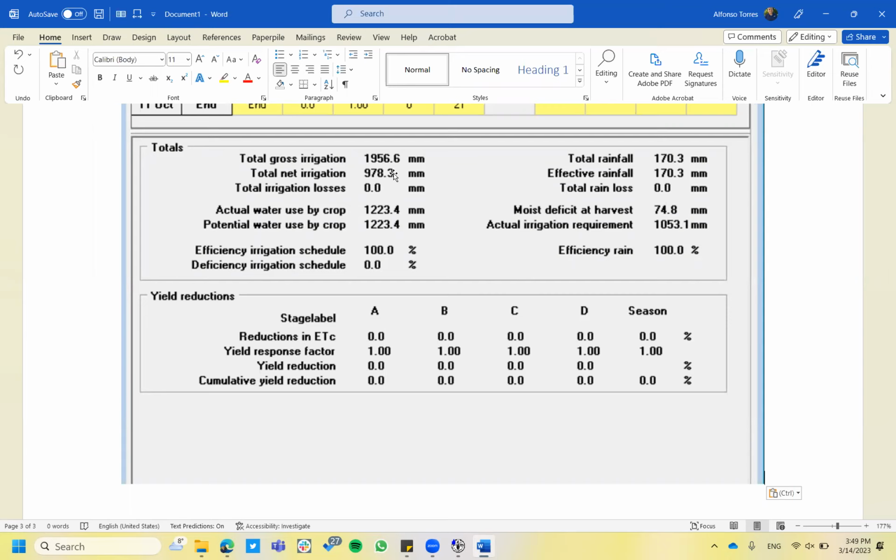So for a surface irrigation field, the 1,600 millimeters here is a huge saving already. So it becomes very attractive, right? But from here to here is 300, and the system complexity is much higher. We need to flush the laterals and repair them when they get hurt or chewed by animals. So there is much more labor in the drip irrigation system than in the sprinkler.